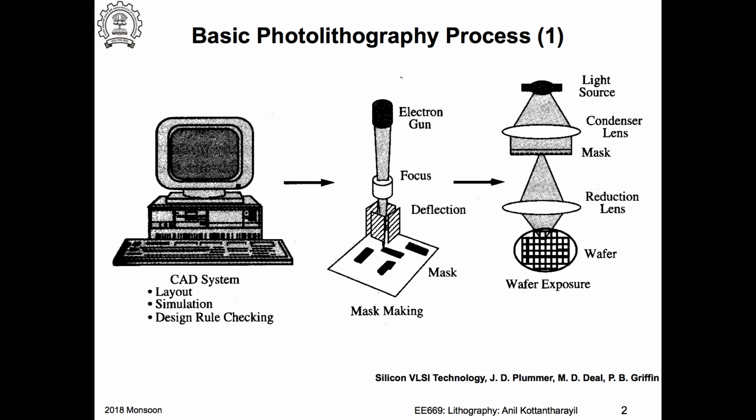So what am I actually saying? Now I have a glass plate where the opaque material is everywhere on the glass. I should retain the opaque material, let's say chrome, here and remove the chrome from these areas. That is part of the layout that I have got.